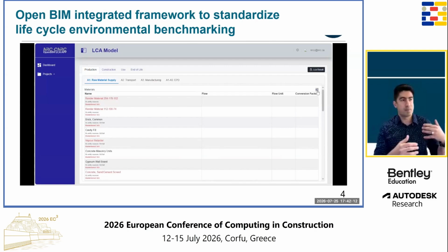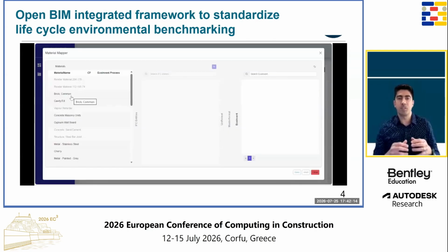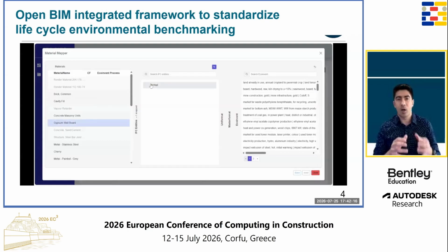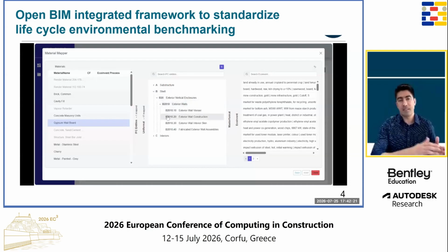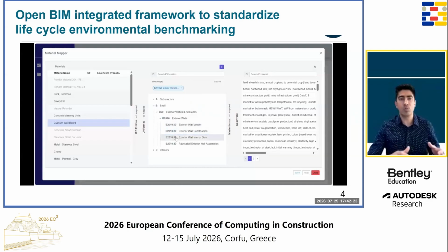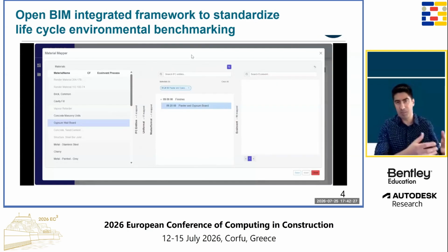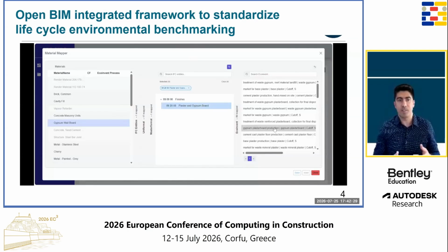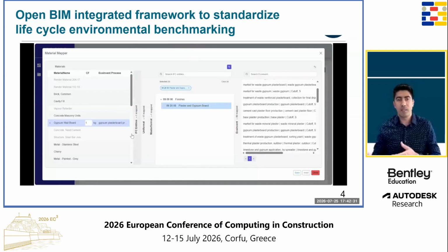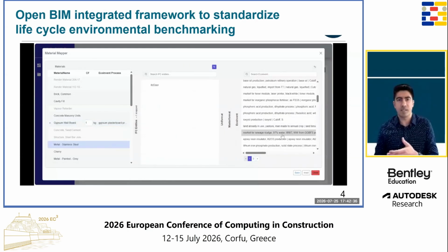We are assessing the IFC submissions against those IDSs to make sure that it has the minimum data requirement. And the next step is how to connect and map the bill of works, bill of materials coming from the IFC files to the carbon dataset, life cycle inventory dataset.